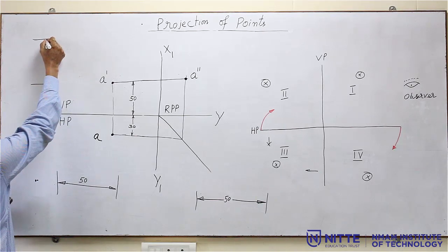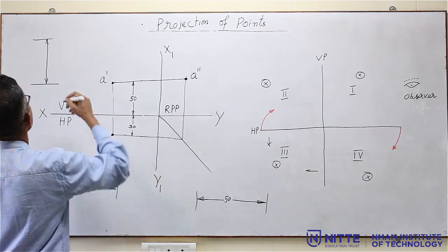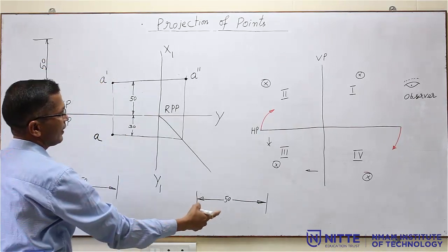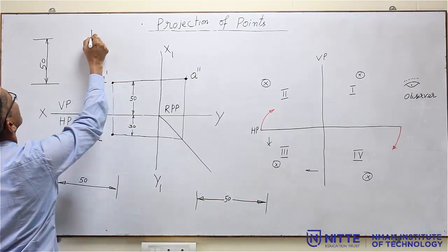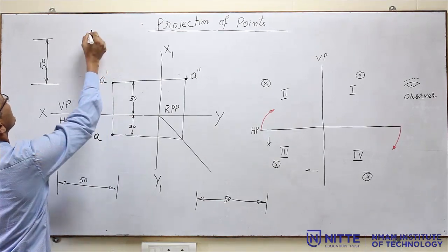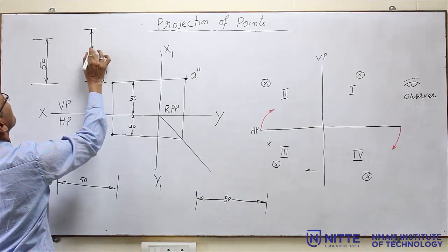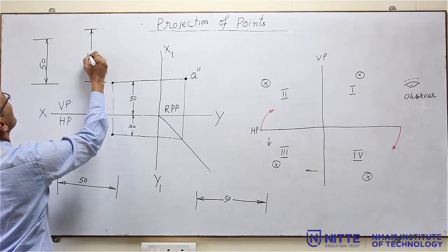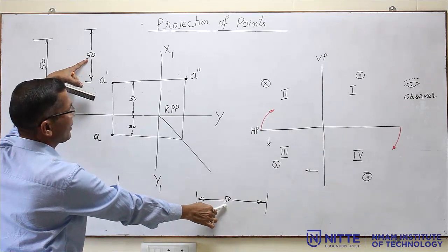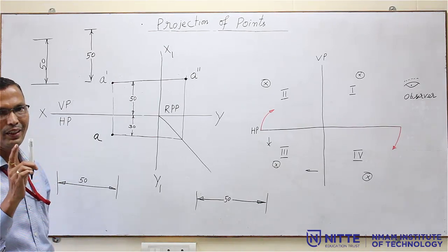This is the vertical line, and in this system, I have to write the 50 like this, and in the unidirectional system, we have to split the line in the middle and I have to write the number vertical only. I have to write the number vertical. You can see here both these two numbers are vertical. That is why it is called unidirectional, only one direction.